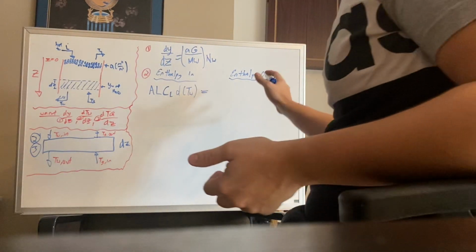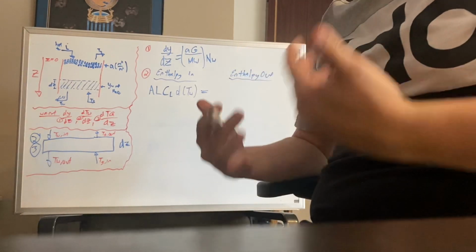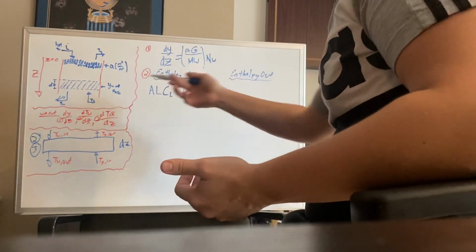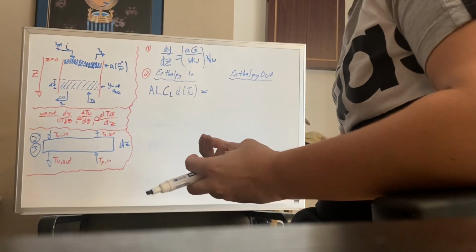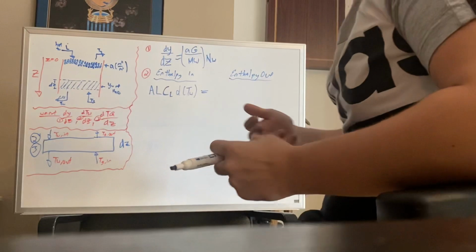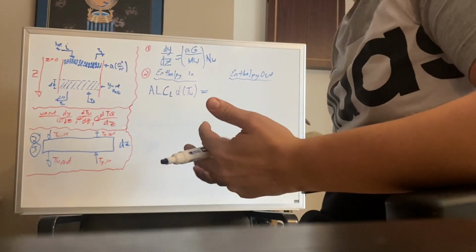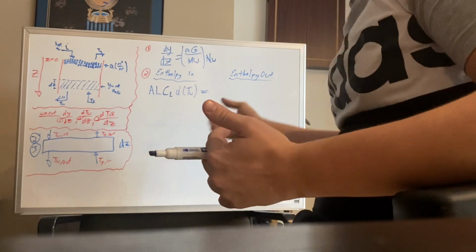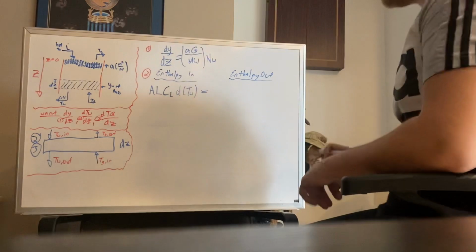And this one's going to be a little longer, because on the enthalpy out side we have to account for the rate of evaporation of water that's being lost in that transfer of energy, because it's going to be losing energy and cooling down. Part of it is going to be evaporating into the vapor phase and going into the gas in the air that's being transferred as well. And so that's why we're going to have an extra term on the back side, and I'll outline that here as well.